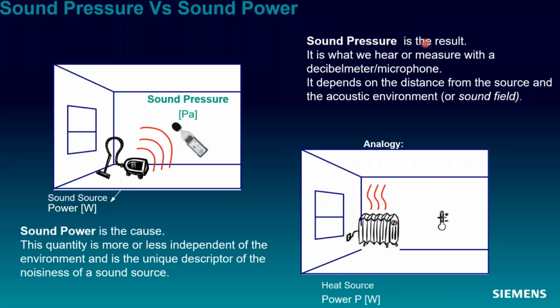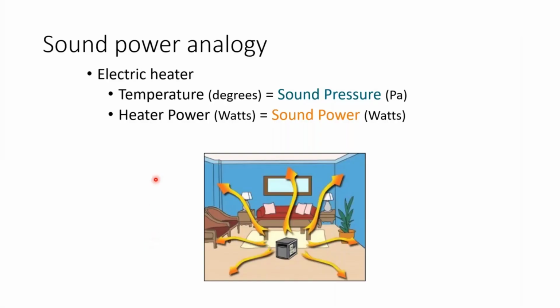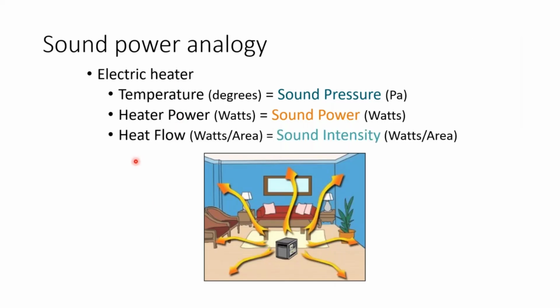So sound pressure, summed up nicely, is the result. It's what we hear and what we measure, and sound power is the cause. It's the quantity. Where that might be confusing is sound intensity. You might be wondering how those connect. We have our temperature and our power, and we like to use sound intensity as sort of the heat flow. It's the direction of where the heat is emanating from, and the magnitude.